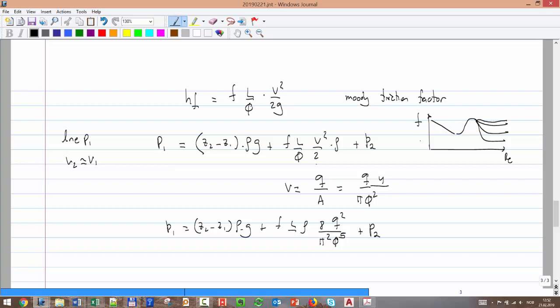So there you have it. You can clear out, of course I'm forgetting P2, I don't know why. Okay, I can clear out P2, and calculate P at the outlet. That's the one we need to use here. We're going to calculate P at the suction of the pump going from the bottom hole pressure, from the bottom of the well. Or we can do the opposite. If we have P2, then we can calculate P1.